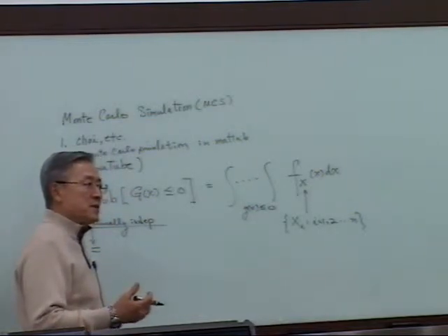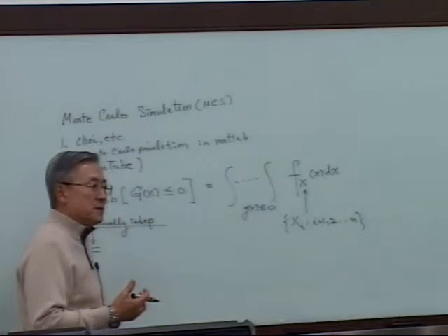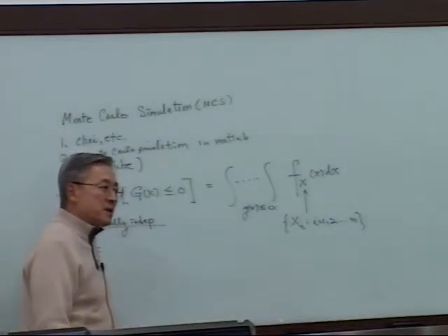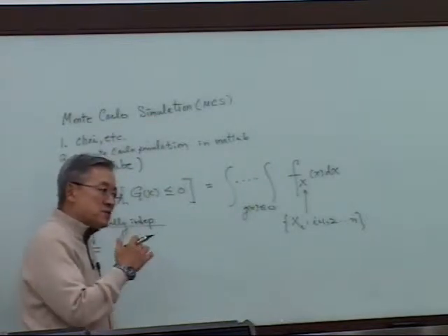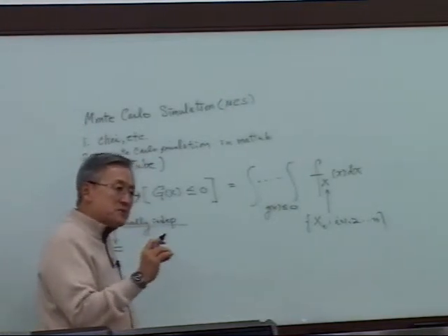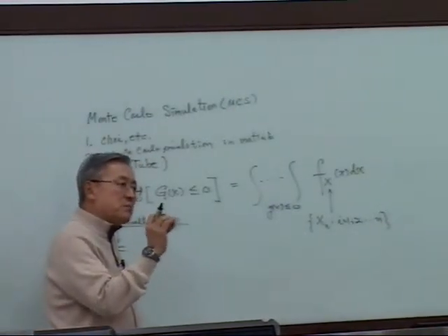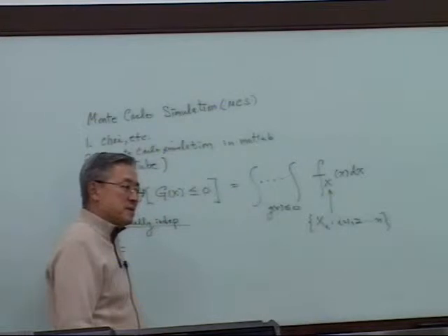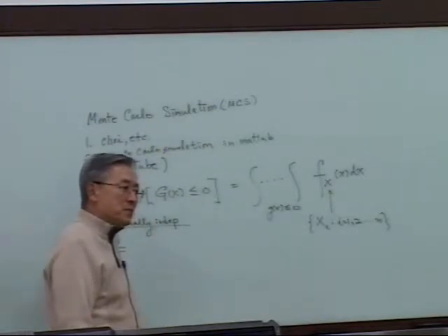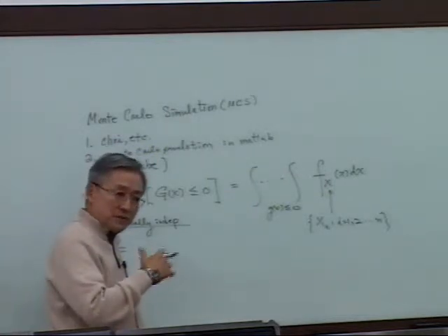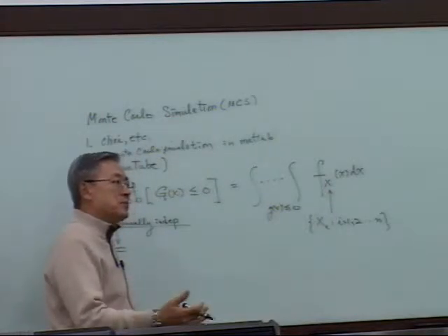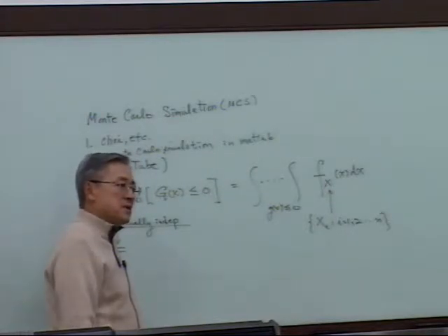The first order reliability method is very nice because you approximate the g function as a straight line. And your concern, my concern, is at the MPP point. But for the second order reliability method, you add an additional term beyond the 2 terms in the Taylor series.